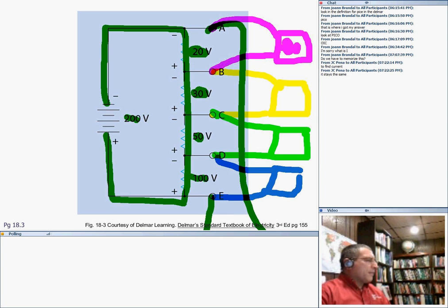They're AC universal fan motors, so you reduce the voltage, it reduces the current, and it reduces the speed. These are a good example of reducing the voltage. Why would I reduce the voltage? To reduce the speed, for one example, and basically to tie to equipment that's rated for different voltages.